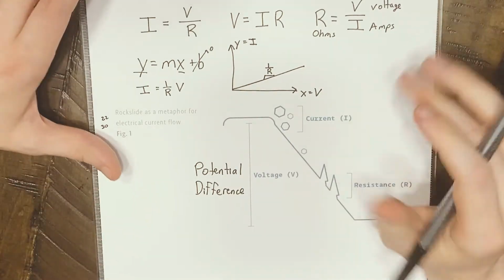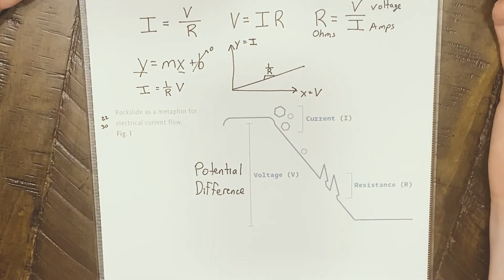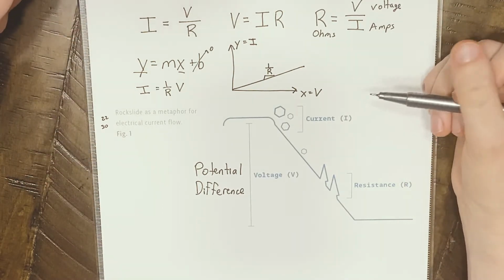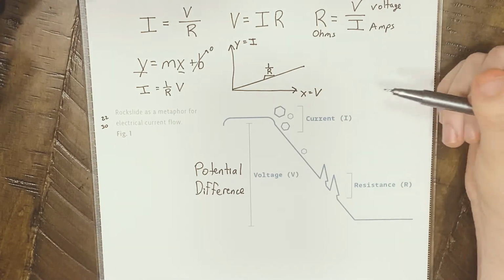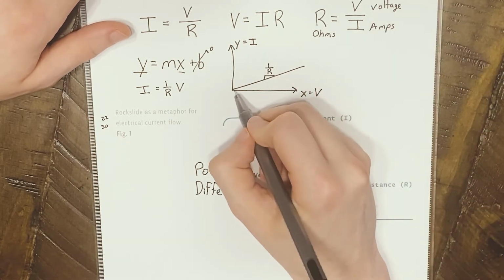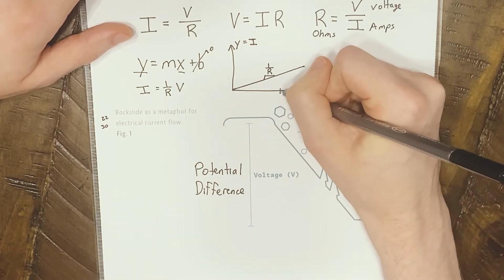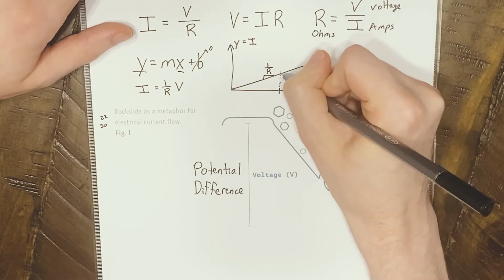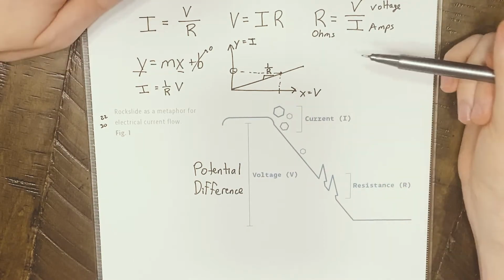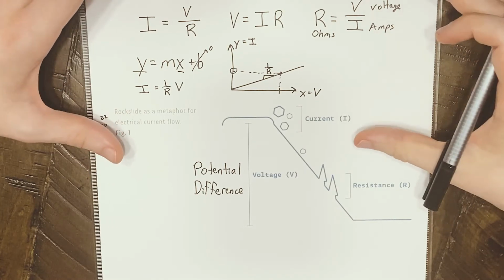Now, this is a more mathematical way to think about what's happening here, to where you have this resistance constant, and you really can think of it as constant in a vast majority of cases because you're only putting in resistors, or you're setting a value for some type of variable resistor and you're keeping it there. You can assume that being the constant, and you have your line here to where if you know a certain voltage, say your voltage here is what you've measured, you go up to here where that collides with the line, go over to there. That's going to be the current you can expect flowing through that component. So that is the more mathematical background of Ohm's law.